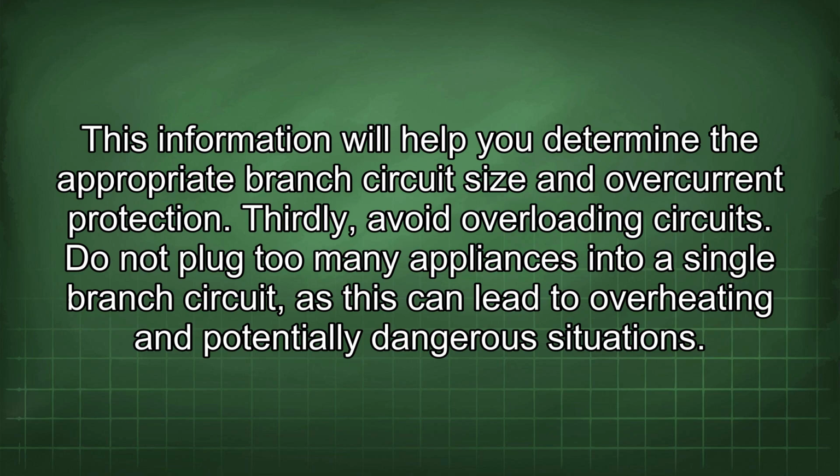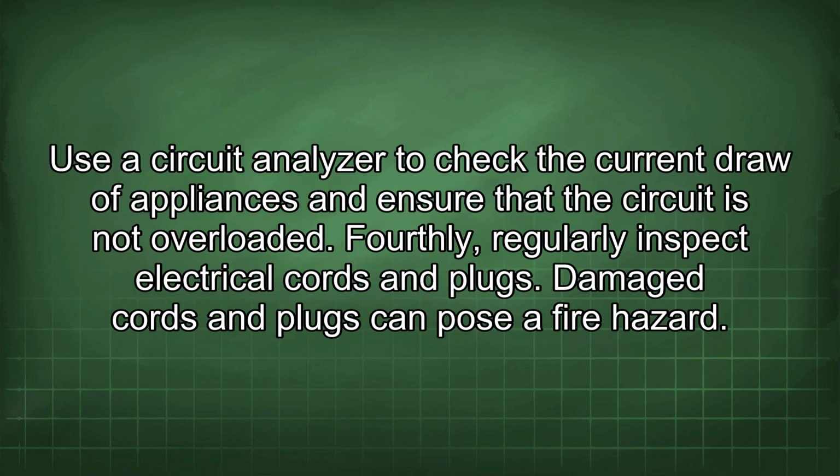Thirdly, avoid overloading circuits. Do not plug too many appliances into a single branch circuit, as this can lead to overheating and potentially dangerous situations. Use a circuit analyzer to check the current draw of appliances and ensure that the circuit is not overloaded.